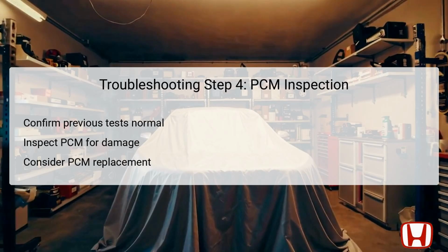During this inspection, check for any visible signs of damage to the PCM, such as burn marks, corrosion, or disconnections. Should the PCM be found to be defective based on comprehensive testing, it may require replacement. This step is critical, as a faulty PCM could lead to further complications and must be addressed promptly to restore